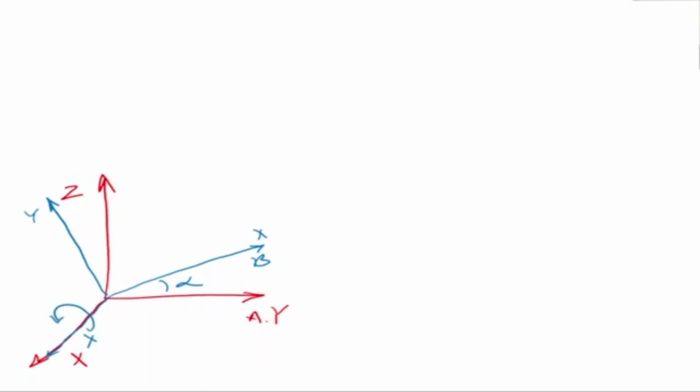Now if I use the same logic, you can actually derive it geometrically. I'll leave that as a homework for you. Okay, if you do it exactly the same way, you make the projections on the x-axis, the y-axis, and then geometrically find out what is the relation between u, v, w and x, y, z. Okay, you can very easily do that geometrically, and what we'll get is the rotation matrix about the x-axis by an angle alpha.